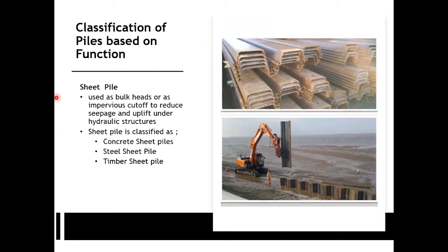Next, we have sheet pile. It is used as bulkhead or as impervious cut-off to reduce seepage and uplift under hydraulic structures. The sheet piles can be classified to concrete, steel and timber.